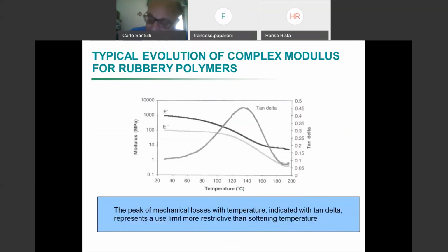You may remember that in polymers we measure Young's modulus, the elastic modulus, by complex numbers. So we have E' and E''. E' is the real part, which we call the storage modulus, the energy stored elastically in the material. And E'' is the loss modulus, which corresponds to damping, to the loss, which means that it deforms more than it should if it were elastic.